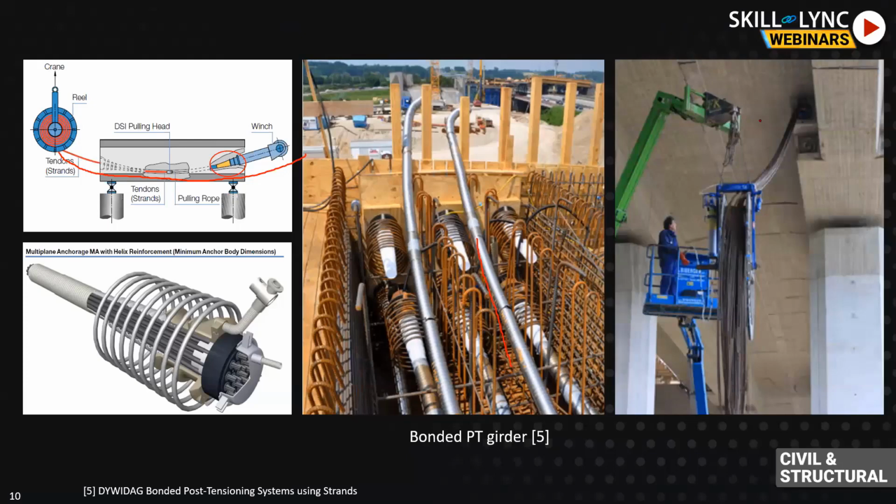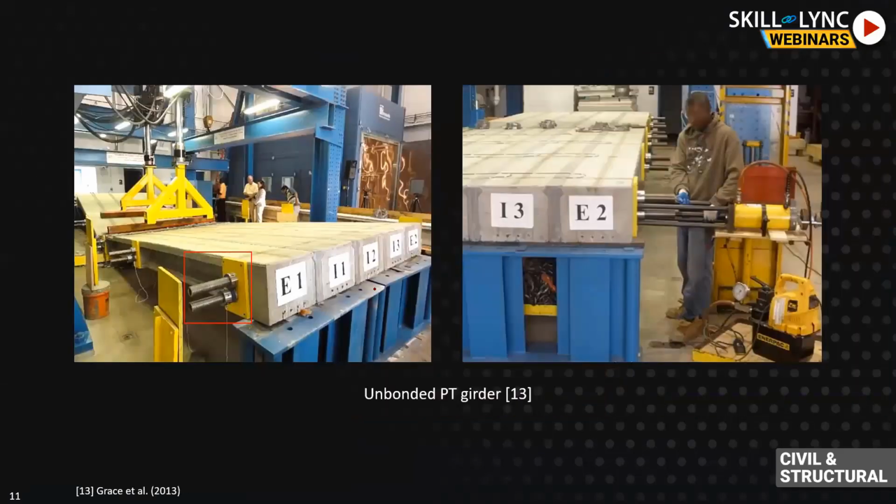You can see in the right side picture, after you pour the concrete, then you pull the structure. So that's why it's a little more versatile. And again, here also the same thing comes into play. Before you stress, you want to make sure that your structure has attained enough strength. This is one good picture where you can see prestressed, unbonded, bonded, everything.